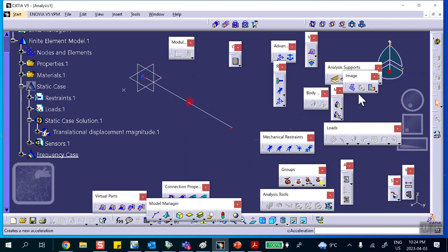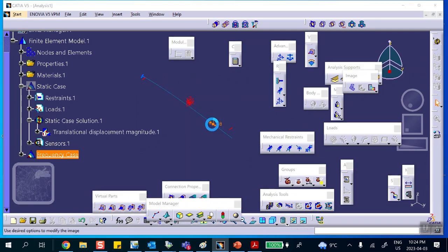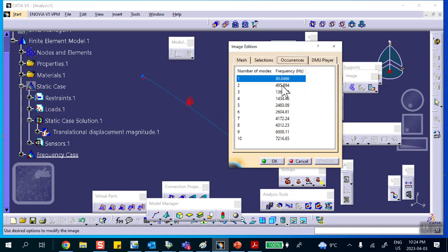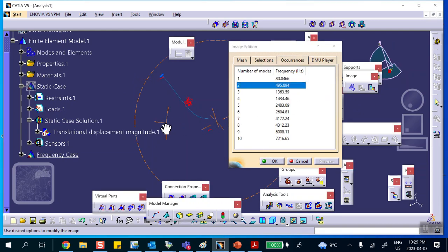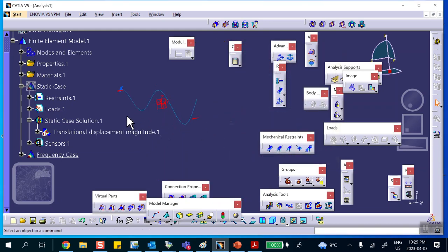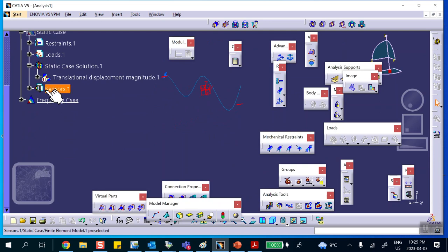Okay, so if you look at the deflection, and if you click on it, these are the frequencies that it extracted. You can see that they're all in-plane bending frequencies. There may be some axial ones too. This one is axial for sure. This is axial. This is again bending. All right, so that's fine. You just leave it the way it is. And let me deactivate this plot.